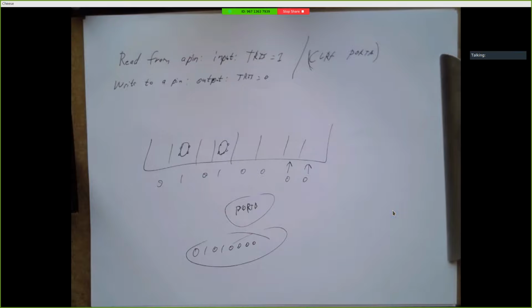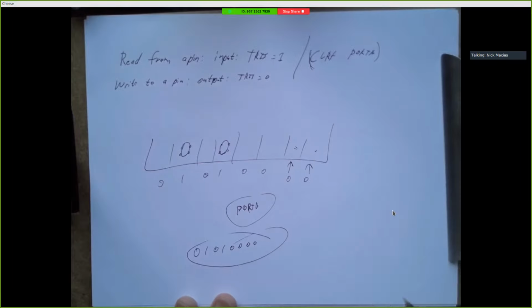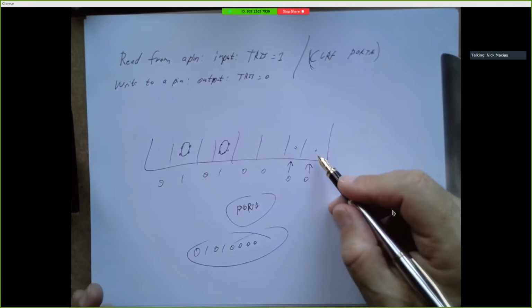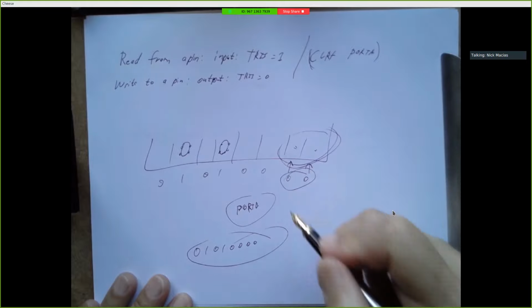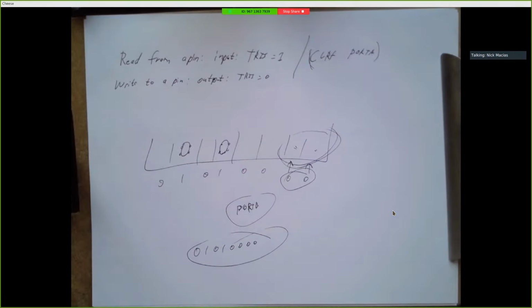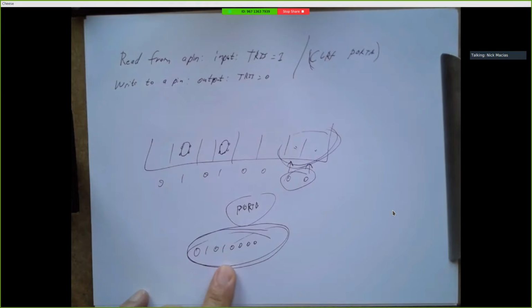Right? That tells me more than just are these two spots empty. To know if there's any cars in here, what I'd like to do is say, is this equal to 00? But I can't just read port B and say, is port B equal to 00? No, it's not. I guess those spots aren't empty, right?